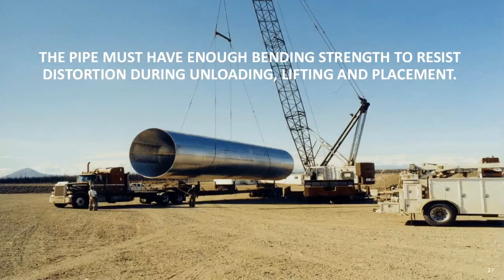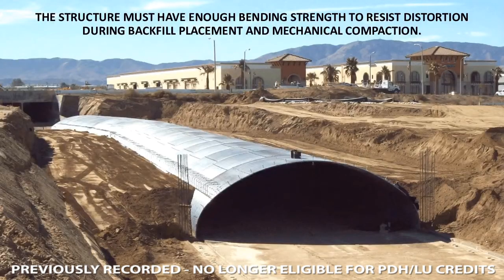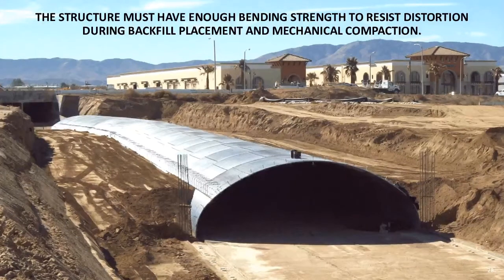You can see here a pipe that has been assembled and is being lifted into place. Obviously, you want to have enough stiffness inherent in the pipe itself that it doesn't deform during the handling and installation process. Also during backfilling, as you're building that embankment next to the structure, there's going to be compaction equipment that's going to be imparting vertical loads to densify that material. Those vertical loads also have a lateral component that will tend to want to distort the structure during construction.